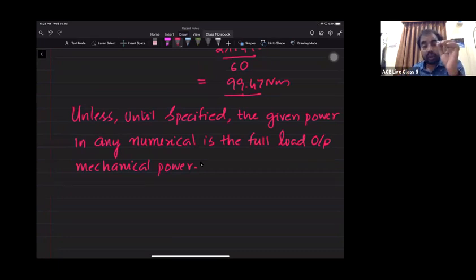So if I want to find out the performance parameters, then I should represent the machine electrically. Why do we need to represent the machine electrically? Among all the calculations, the electrical calculation is the simplest. So that is the reason we need to represent the machine electrically. As of now, we have represented the induction machine with respect to the rotor side. And with respect to that rotor side, if you want to calculate anything, we have some formulas.